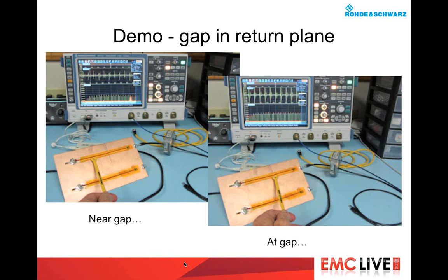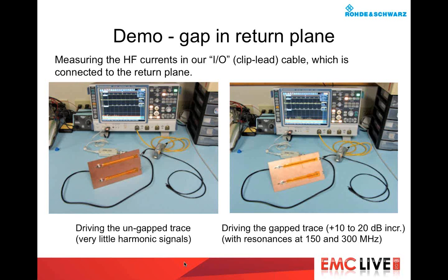Now there's another interesting experiment you can do with this board, and by the way, these are easy to make and use to demonstrate the concepts to your colleagues. What we've done here, in the left picture, I have attached a 1 meter long clip lead to the plane of the board. It doesn't matter where you connect it. It can be connected anywhere on that return plane. And I'm driving it with the comb generator.